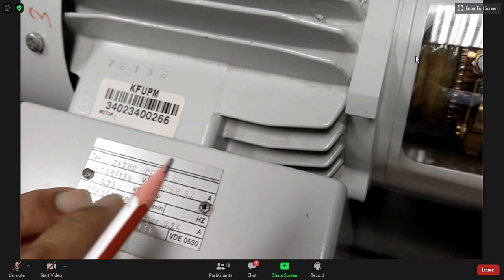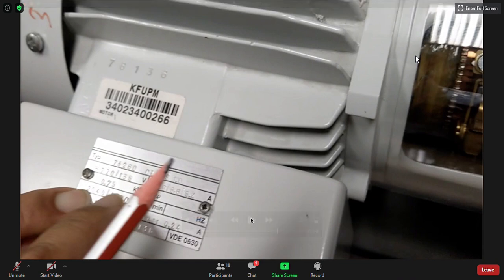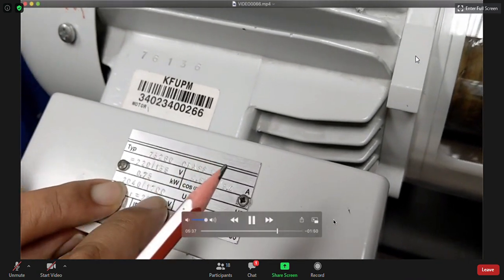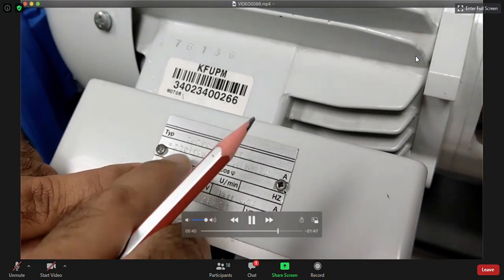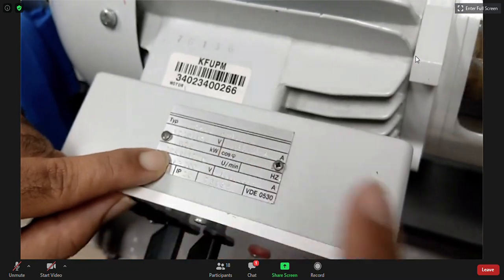Similarly, we don't have frequency because frequency is 0 for this DC machine. So you can see that we are filling the table which is in your manual. You can open your manual and see it. And just filling the information from the nameplate of the machine, you can observe this. At 135 volts, it is supposed to work at 1700 RPM. At 220 volts, it's designed to work at 2040 RPM.